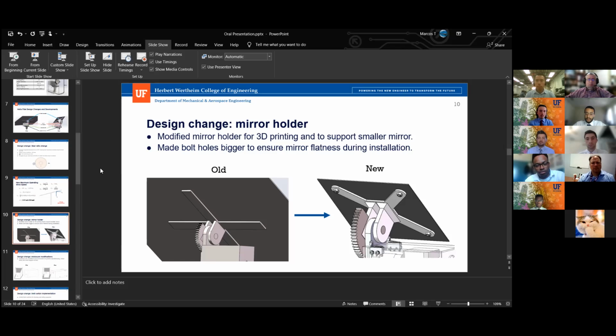Okay. Because when I heard you guys talk in the presentation, you said we install by drilling a hole, and then when we install, there is tension. And what I feel is, when you drill a hole, it's not perfect drilling, there can be micro cracks around it, and now you have tension, you have stress concentration around the hole, and you have micro cracks from drilling the hole. That can cause potential risk. So yeah, I appreciate your explanation. That's all my question. Thank you. Thank you.